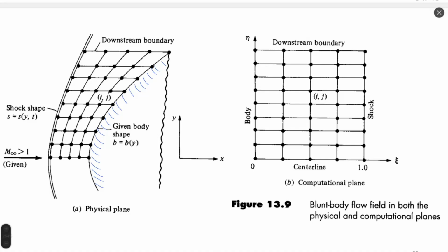For two-dimensional flow, this is not very typical because two-dimensional flow converges relatively fast, but for three-dimensional flow, this could be extremely important, when we can save thousands or even millions of cells which have no contribution to the solution, which are just staying inside the simulation. Even if cells are somewhere here in the constant flow part, they are still calculated. Calculation happens in all cells, even if all flow parameters are constant and the same everywhere.